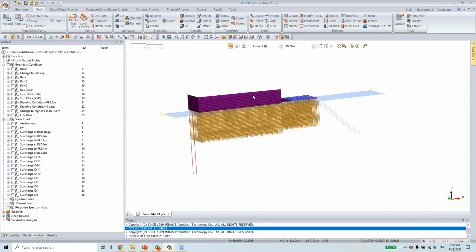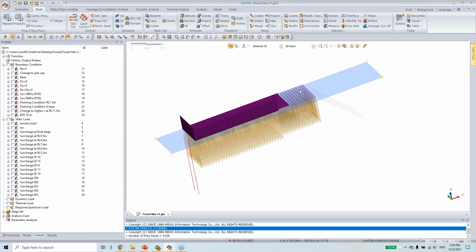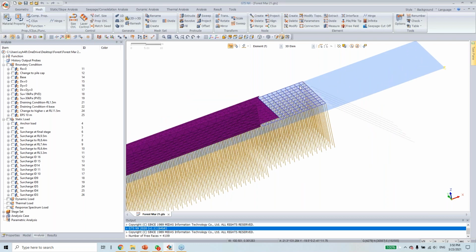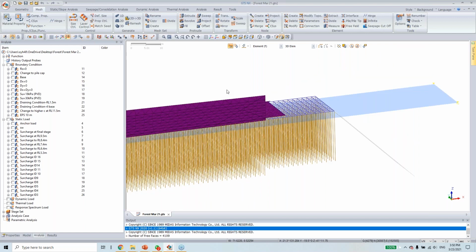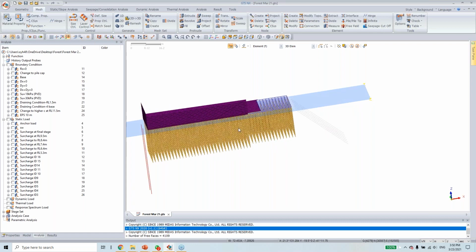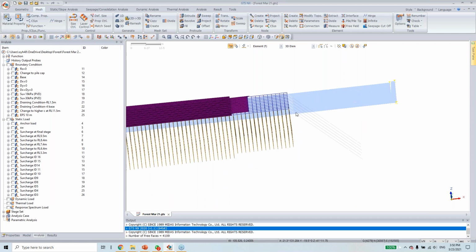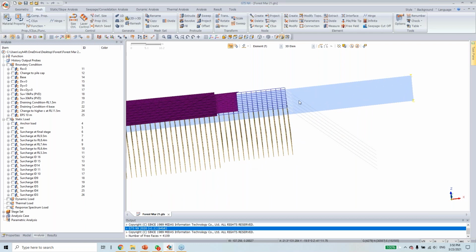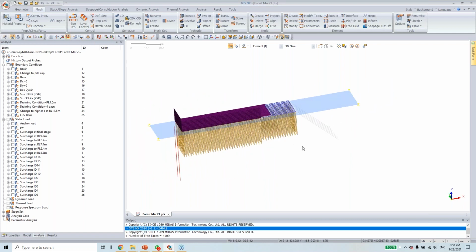These are the reinforced soil wall facing, and this is the grid beams designed by the local engineers. We just aim to find out the root cause of the large movement. Behind the grid beams, there are anchors. You can model the free length and the fixed length. All right.